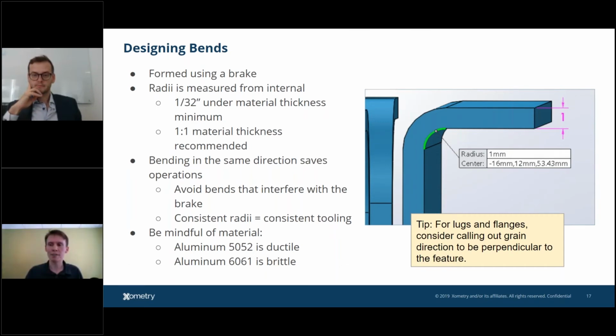On this graphic, I also wanted to show a back gauge here, because typically in manufacturing sheet metal parts, I'm going to be taking a flat piece. I have this gauge already calibrated to the right location. I bump up my part against that gauge, press down, create that feature. So that's just something I wanted to point out as well.